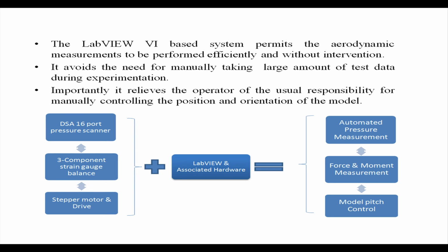So, the functionalities are pretty small in number. In complex experiments, there could be a large number of functionalities, and the experiment may actually be done in a more complicated way, in the sense that there could be a situation you have a model with 100 ports, but your pressure scanner only has say 36 ports, and now there could be manual error, that when the person who is handling all this connects port number 1 to 36 and then acquires the data through the VIs. Next shot he should be connecting 37 to say 72, but by mistake he does something else.